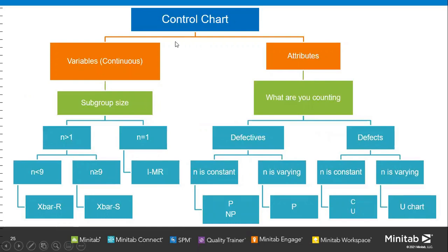We have variables control charts and attribute control charts. For today, we look at attribute data, something like defect or non-defect, accept or reject. Then we look at the P and NP charts, or C and U charts. So if you face attribute or categorical data, no worries, you are also capable of doing a control chart to see whether the process is stable or not stable.